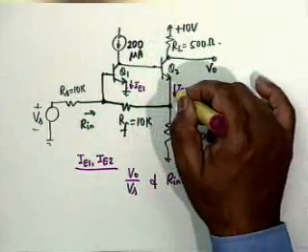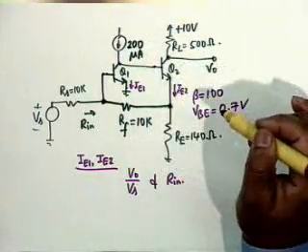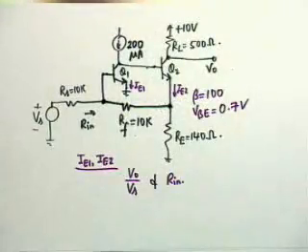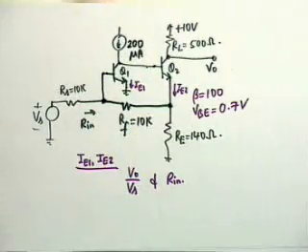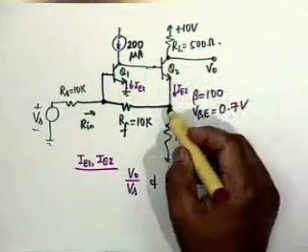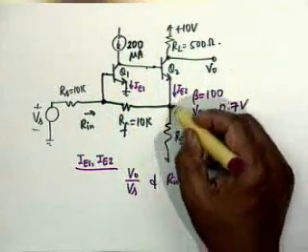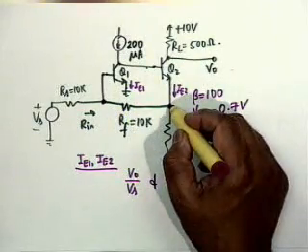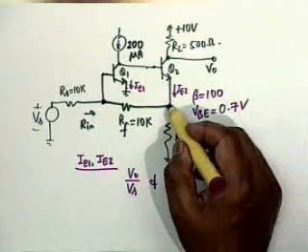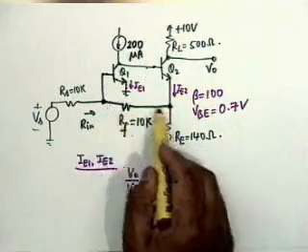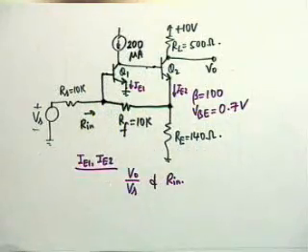You don't ignore it now, because this will have to be compared with 200 microampere, this is a constant current biasing. There is a temptation to ignore this. Then that current minus the current that goes through here is dropped across here. So you know this voltage. This voltage can also be written as the drop in this, plus 0.7.